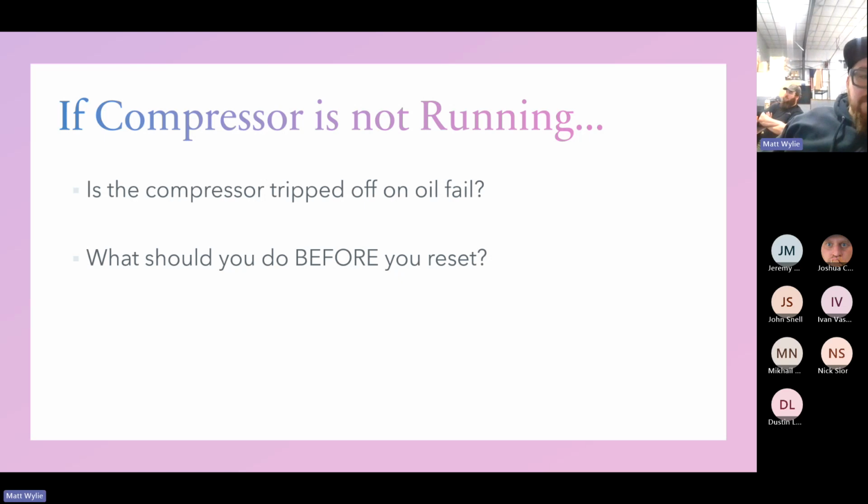If the compressor is not running, is the compressor tripped off on oil fail? What should you do before you reset? Like oil fail, a lot of the semi-hermetic compressors, like at Costco's and a lot of grocery stores, they have the oil fail.